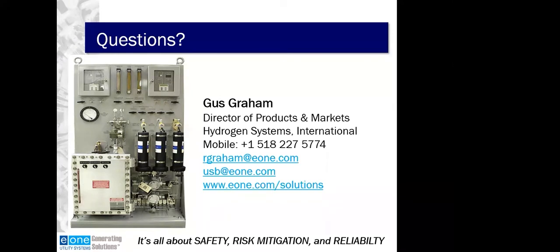So clients frequently perform a calibration with just one gas, which is H2. How does this affect the measurement? That's a great question. I'm going to assume one of my colleagues threw it at me because I forgot to mention that. Yes, calibration must be done with all three gases.